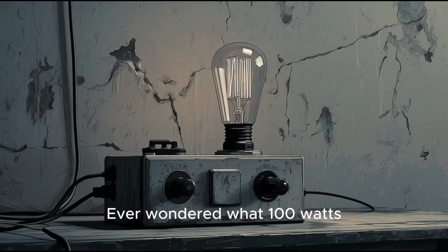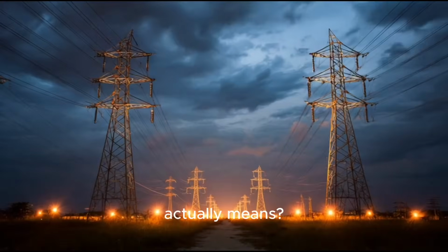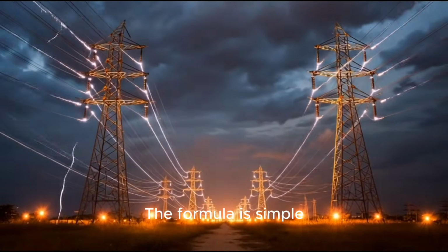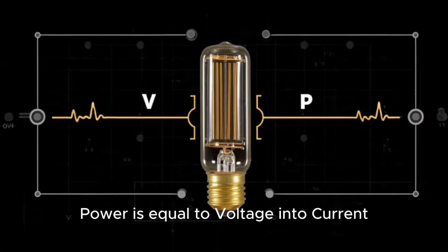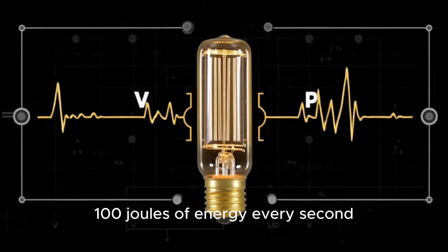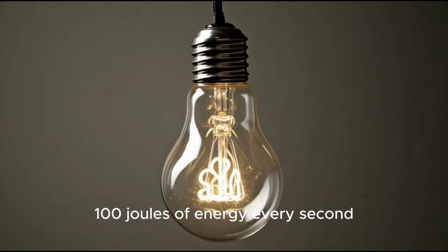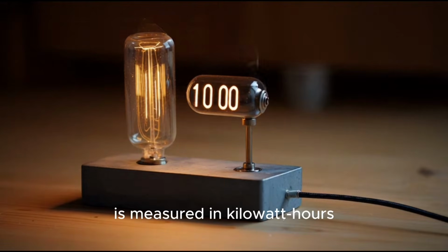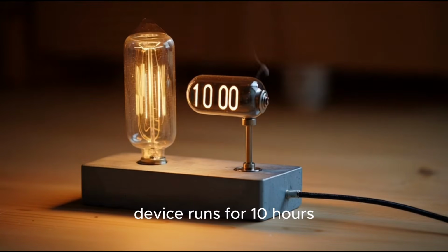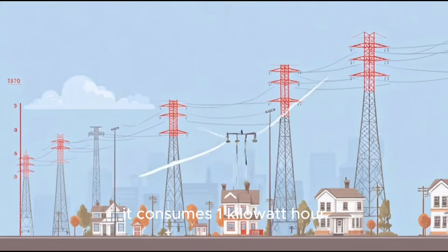Ever wondered what 100 watts actually means? Electrical power is the rate of energy use. The formula is simple. Power is equal to voltage into current. A 100-watt bulb uses 100 joules of energy every second. Energy consumption is measured in kilowatt-hours. If a 100-watt device runs for 10 hours, it consumes 1 kilowatt-hour.